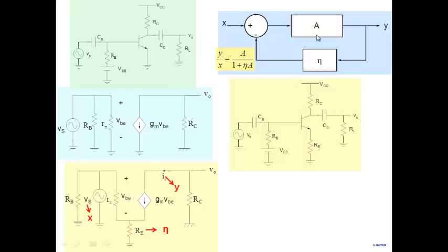This is the same picture that you see here: by putting an RE here, I get negative feedback. Now that we have seen how negative feedback works, please think about how it was helping. The negative feedback was distorting what was appearing over here, causing a distortion in the signal which appears between base and emitter. That distortion then gets compensated by the transistor's distortion, and you get a nice sinusoid at the output. Very interesting way in which this is working. All right, so let's stop here.